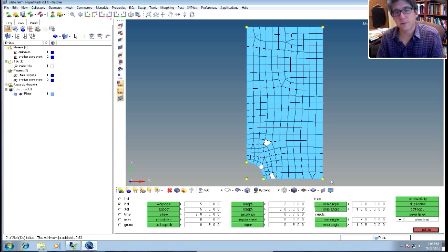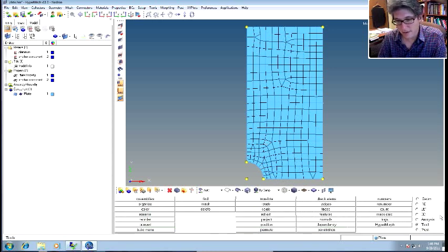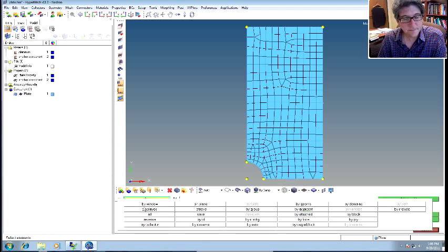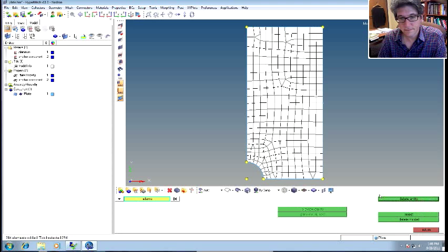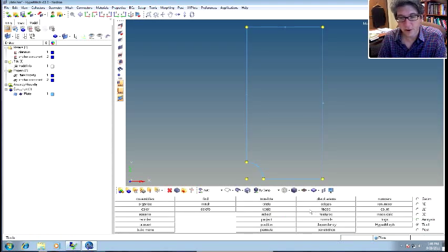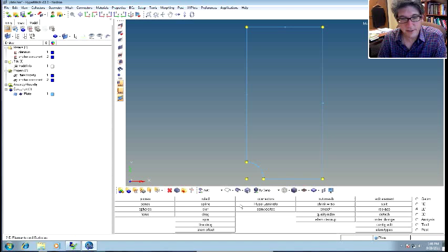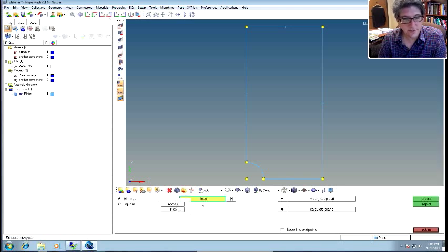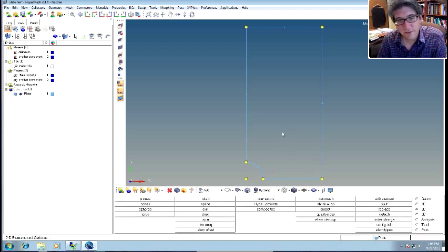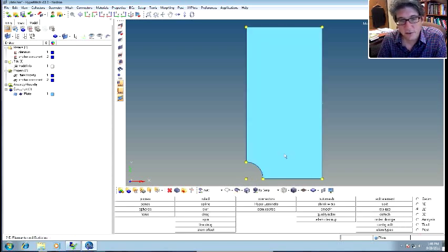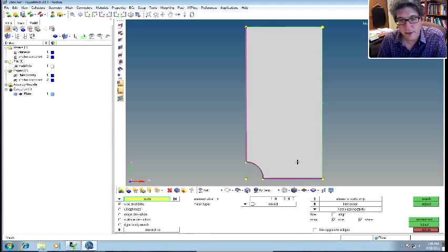Now, probably the easiest thing to do is just to refine the mesh everywhere. So, the easiest approach, let's go back and delete the elements again. Is in fact just to go in and really refine the mesh completely. So let's go back and pick planes. I think this surface already exists. Yeah, okay, whatever. Pick the lines again. Well, actually, I think that surface exists, right? There's a surface there. So I can directly mesh that surface using auto mesh.